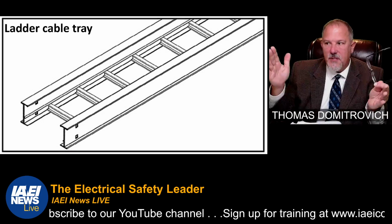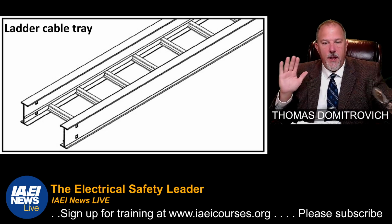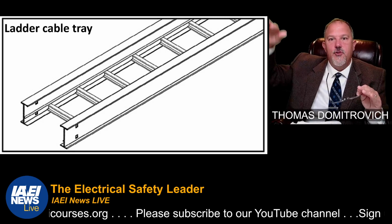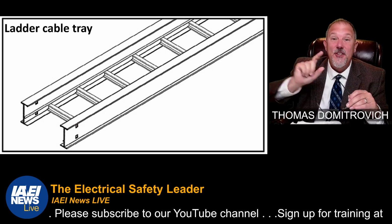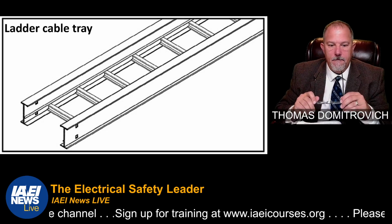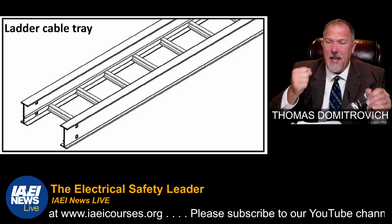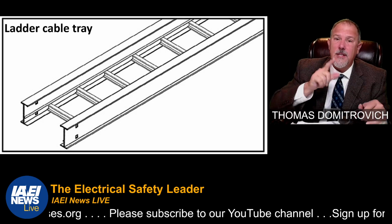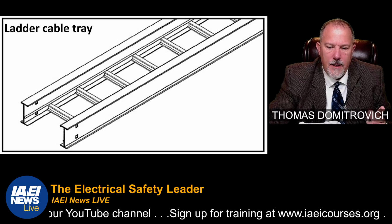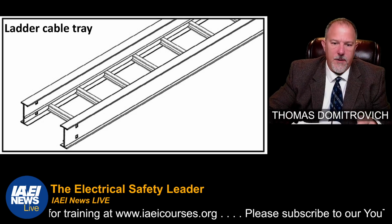You've got to think about the distance between those rungs, the distance between the side rails, the width, right? If your rungs are too far apart, you can get cable drooping. You don't want droopage inside your cable tray. So be mindful of the rigidity of the cable itself, especially small conductors. You've got to think about the small conductors and the proper distance between rungs. I'll just leave it at that.